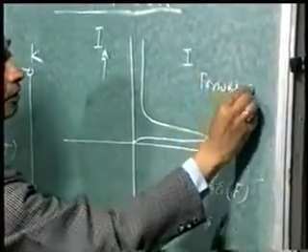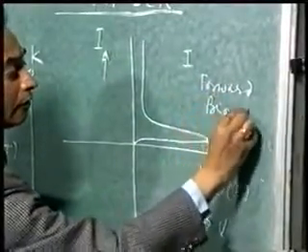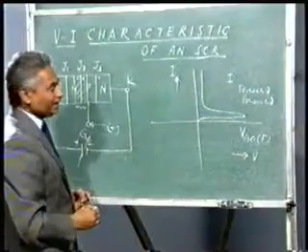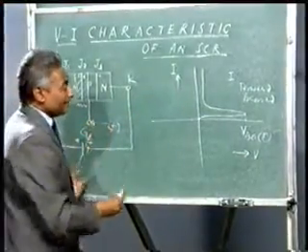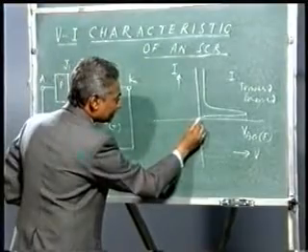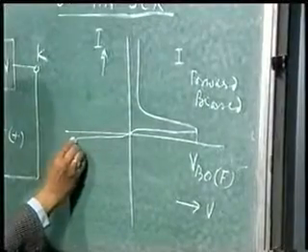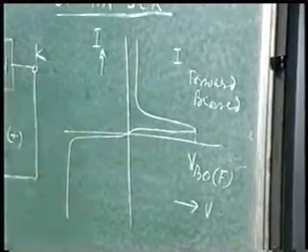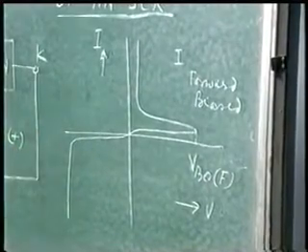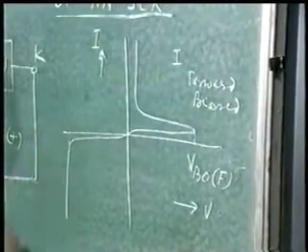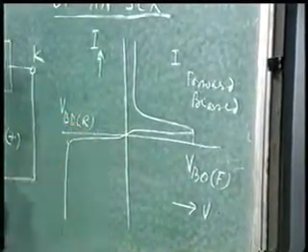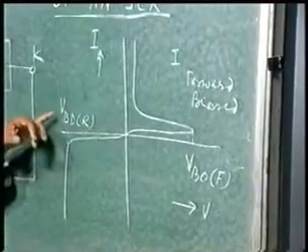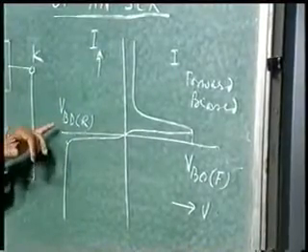Forward biased condition. Okay. Now if I go reverse biased, what will happen? Reverse bias also will go like this, and suddenly there will be a very high inrush of current at this point, and this point is known as VBDR, means reverse breakdown voltage. Now there is a meaning here, breakdown.